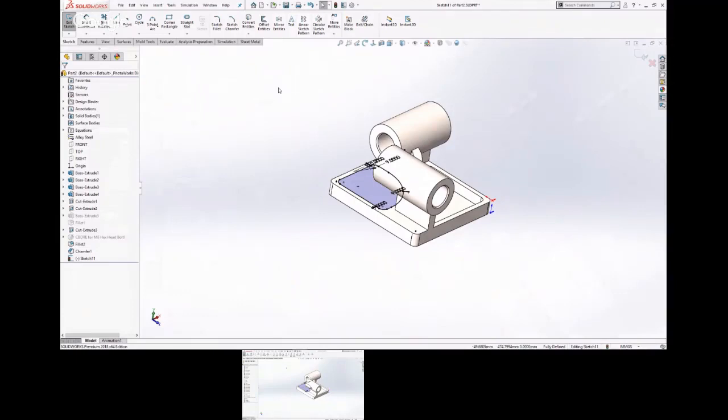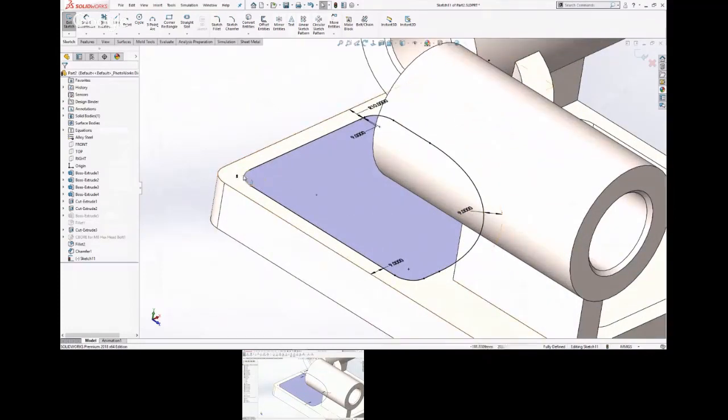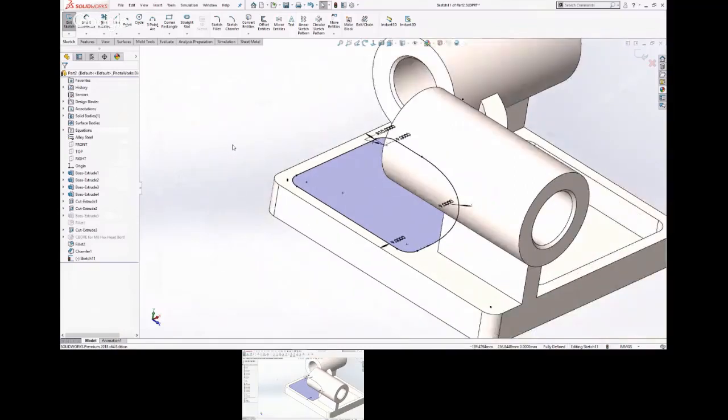But like you said, you went back to classic mode. So again, the reason I brought that up is because you see those two dots right there. It almost looks like a sketch entity there, huh? And that'll screw things up. Visually, I should have known it wasn't because I see the sketch contour in here, that blue thing. That's telling me that it's a closed contour and it can do something with it. So sketch contours are pretty cool. That came out of a CATIA product actually.